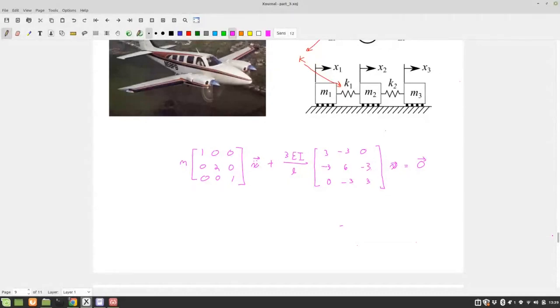Yeah, right. So this whole bit here is your M matrix, and this whole bit here is your K matrix. But I pulled out the constants because we just don't apply them, and it helps with the eigenvalue solutions. If you had values, you could put them in, you would get the same answers. It's just everything normalizes out in your mode shapes. Does that make sense?